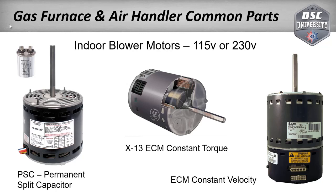Then when we get to the top of the line, the ECM motor, it's an electronically controlled motor, and it has all the bells and whistles. You can go in through either your dip switches on the control board or through your thermostat, and you can make all kinds of adjustments with this blower motor. You can do a whole lot more things with it. You can control how it turns on. You can control how it turns off. It ramps up. It slows down.